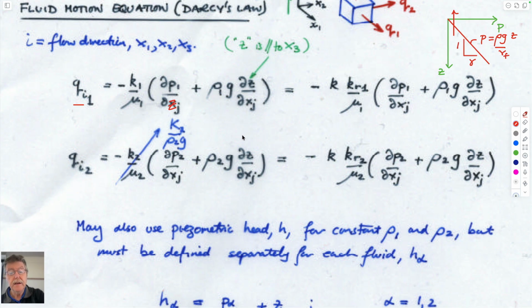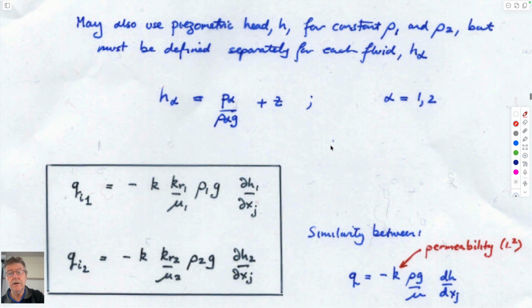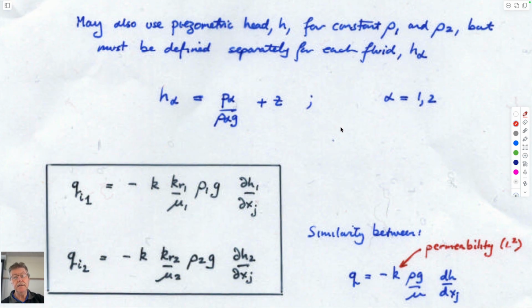And so what you have to do is substitute the magnitude for this unit weight. And I guess where that comes from is that we can define flow rate in terms of hydraulic conductivity and a head gradient, dH/dx. This is how Darcy first defined it. This is a velocity. This is in meters per second, also velocity. And this, by definition, is dimensionless, length over length.